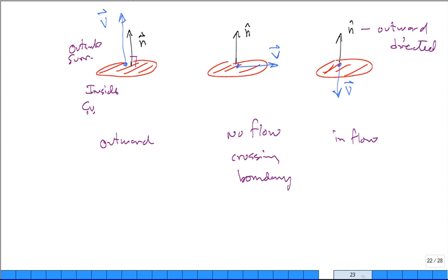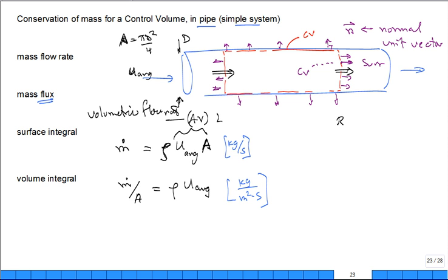Then we're ready to be more sophisticated and talk about not just saying this is m dot in here and this is m dot exit there. We can do one calculation. If you want to get the rate of flow across the boundary of the surface, I would do an integral around the whole area, the control surface. What does CS stand for?